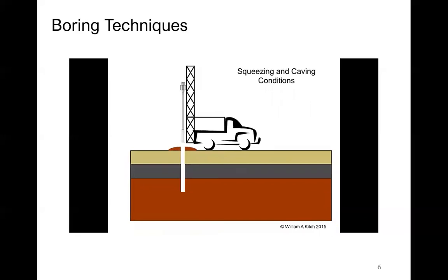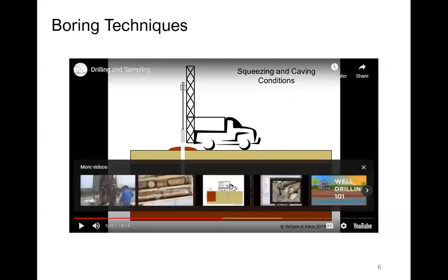The open hole method only works if the soil is stiff enough and strong enough to remain open after the augers are removed. So while in Florida it is often possible to use the open hole method, many times the soil is not able to maintain an open hole.